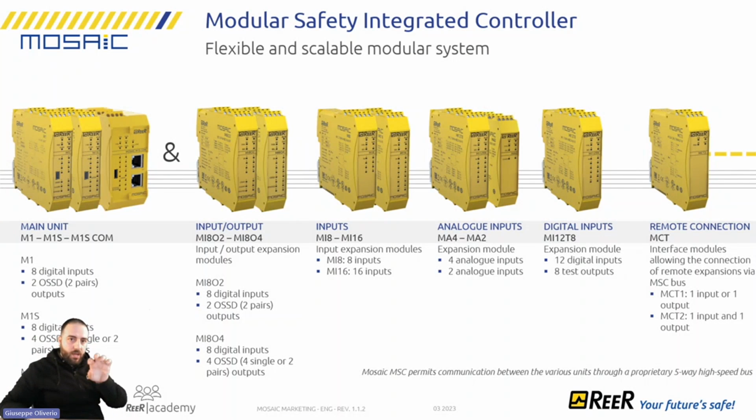Then, if you use the M1S COM and you want to exchange data with the PLC, we will send the PSI value to the PLC. So also from the software point of view, the software engineer doesn't need to scale anything, to swap bytes or to do some conversion to the signal, because we are able to provide the engineering unit.